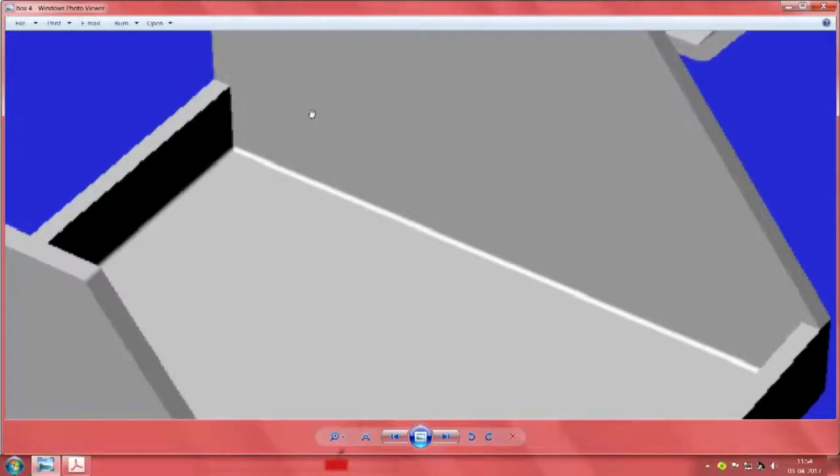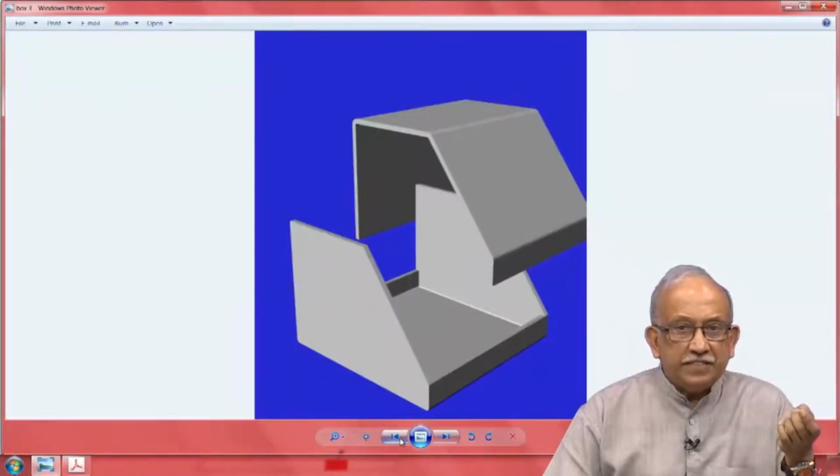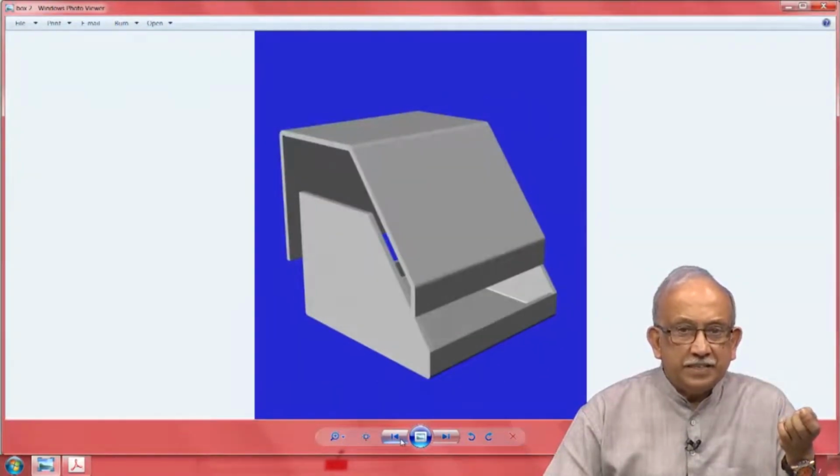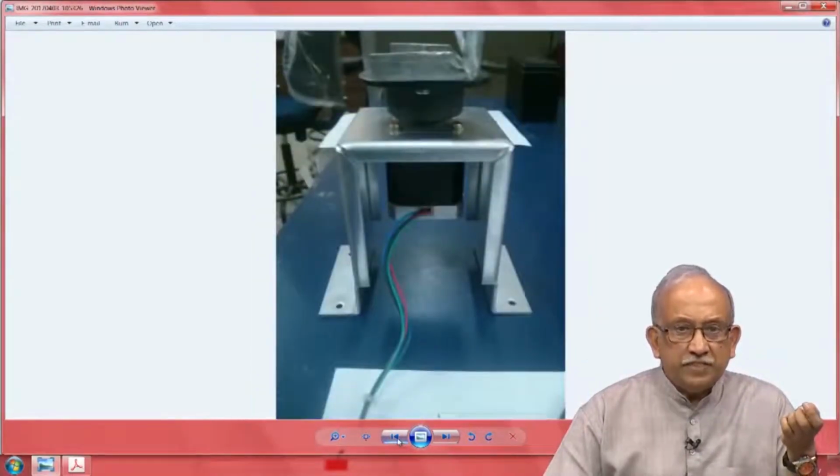But here again you notice, we talked about spring back. When you want that spring back, this U needs to bend in a little so that it can come out, and in this corner you need a small gap to ensure that the bending takes place without any problem. Understood, no? So in the corner a small notch is required. Usually these are details to be done by the fabricator, but it is still useful for you if you can follow these things.